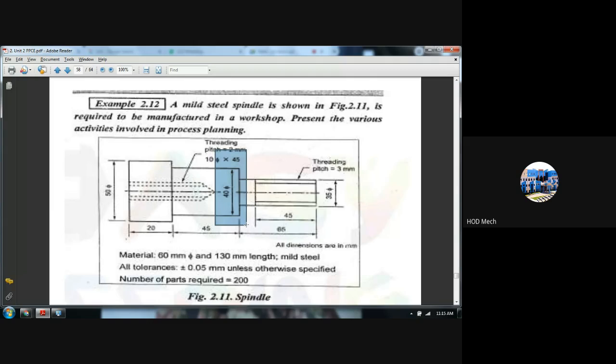Workpiece rotate பண்ணும்போது பிடிக்கிறதுக்கு அந்த grip கிடைக்கிறதுக்கு இடம் இல்லாத பட்சத்துல they will go for separate operation on this outer threading. இத கடைசி ஆப்ஷனா வைப்பாங்க. So it all depends on how the process planner visualizes this approach.